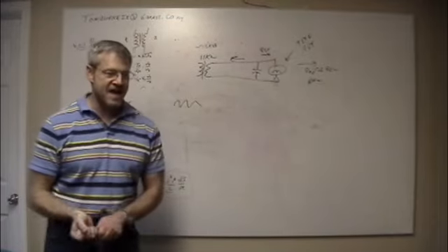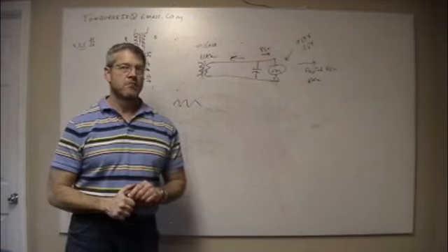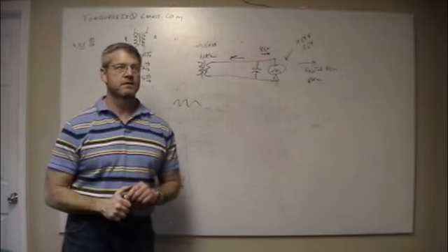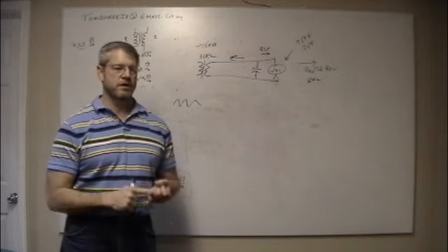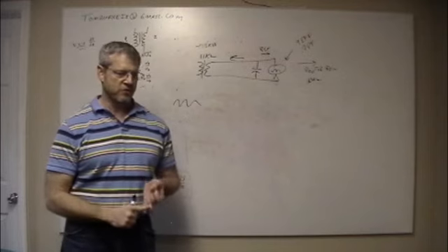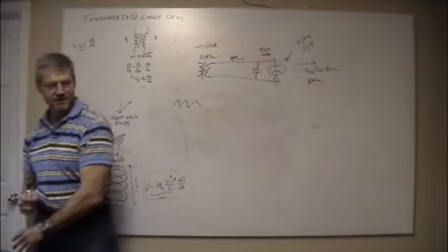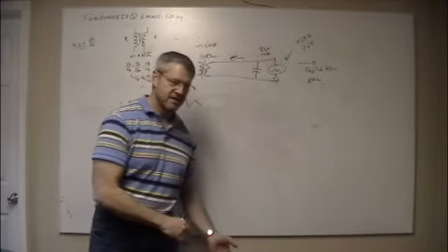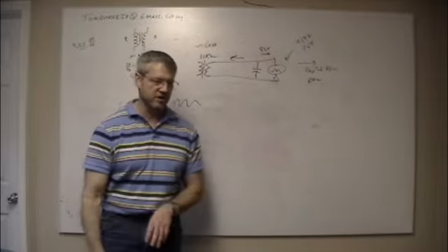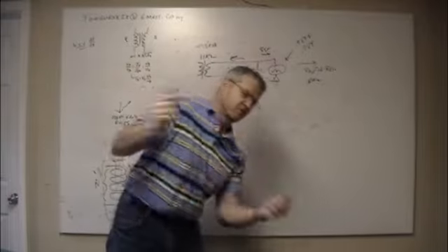Now what you would see happen is if you run motors at idle, it's really weird. Motors are designed for a load and an RPM. And if they're running at that load and that RPM, their power factor is really good. But if they're off of that, if they're just starting up, their power factor is bad. Or if they're running with very little load, their power factor goes the other way because the inertia of the system tries to work against it.